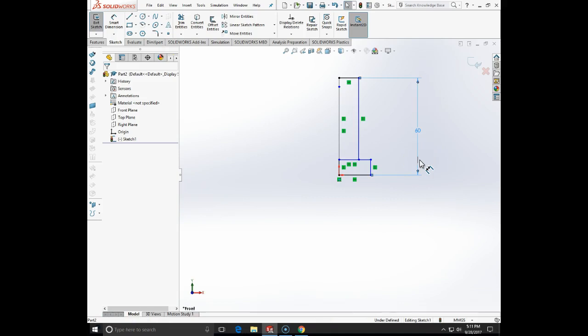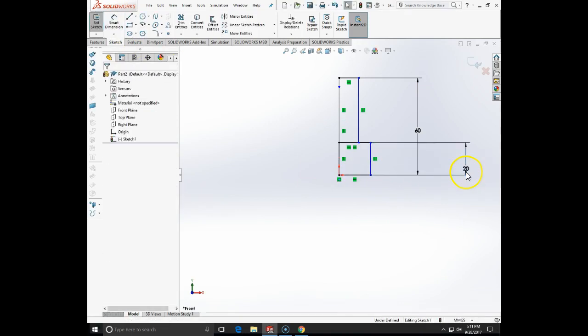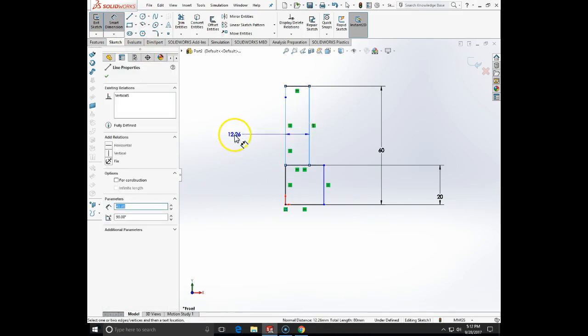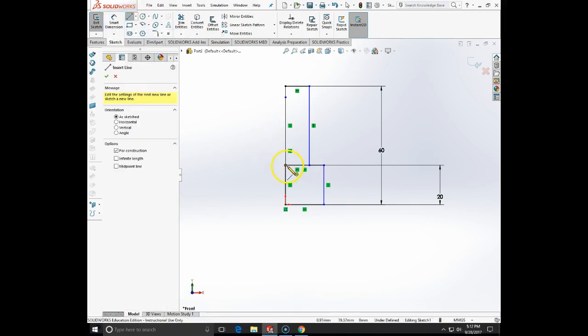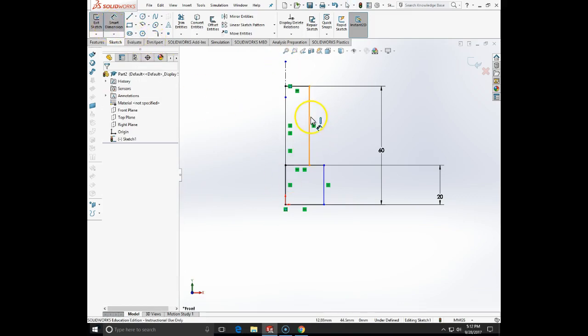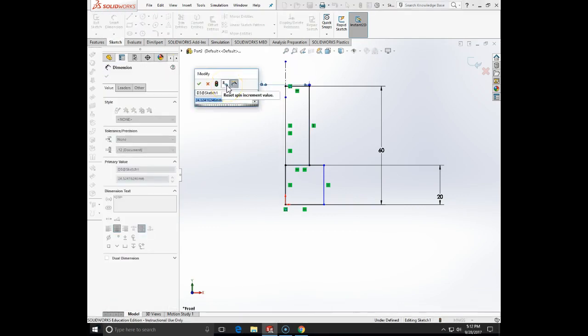I'm going to specify that the thickness of the base of the block base is 20 millimeters. And now I'm going to specify diameters. And the diameters that I'm going to specify first will be for the top. I'll need to extend a little bit my center line. So I can use the center line to specify diameter by clicking on the outer edge, clicking on center line and pulling on the other side. My top diameter is 60 millimeters.